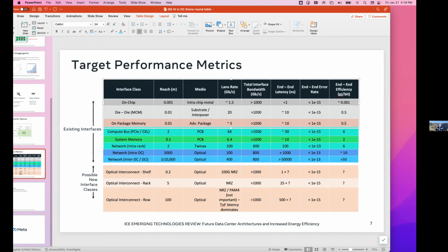There's this fear of double rate refresh on HBM, but it's actually only a 7% hit, I hate to say it that way, on the delivered memory bandwidth. And it opens up a whole lot more temperature range. So there's a trade-off. I think we're going to have to use all the knobs that are available before we ever get to using optics to disaggregate HBM.